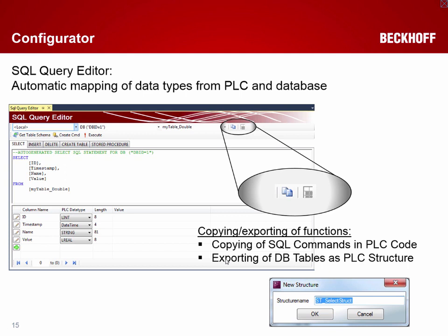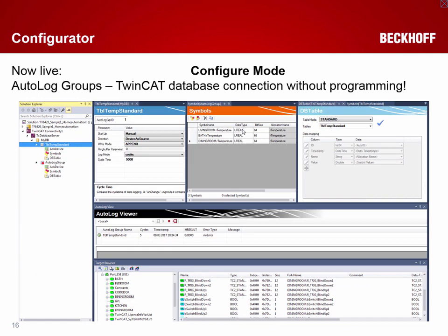It is also possible to convert the commands you can see here, in this case again a select command, into PLC syntax, and then you can copy this by these buttons to your PLC project, and then you can try it from there. So very nice, this tool to test the complete communication with the real database server in the field.